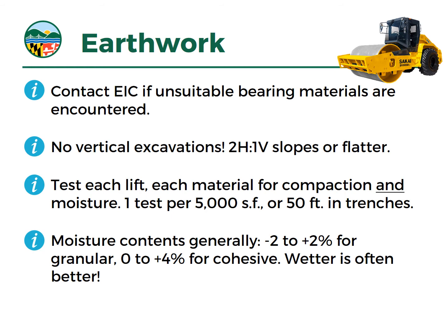So first, we would recommend, if there are unsuitable bearing materials encountered, contact the engineer in charge and get some direction on what the appropriate method to deal with that bearing material is. Again, we'd recommend not performing bridge lifts, but maybe it's just disking and drying. We wouldn't recommend soil amendments like concrete or lime. That can result in a more brittle embankment, which is more prone to cracking. But there are a lot of options to deal with difficult subgrade materials.